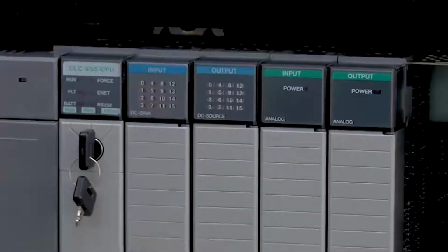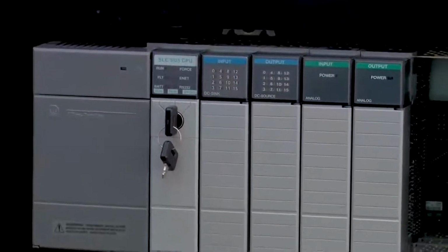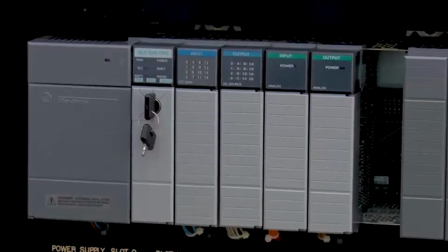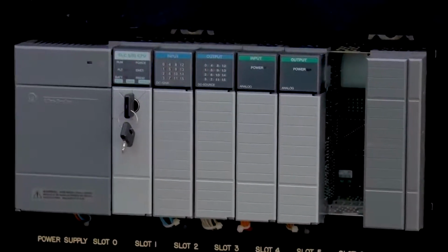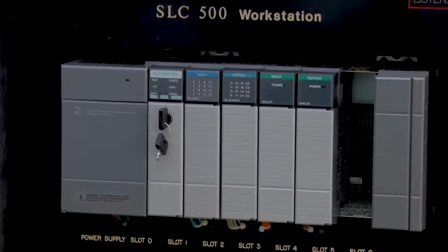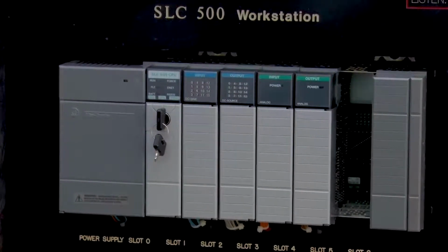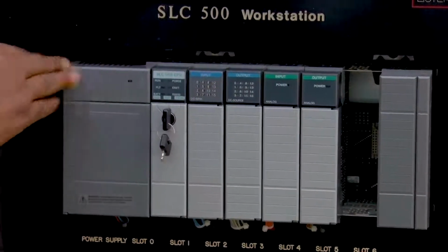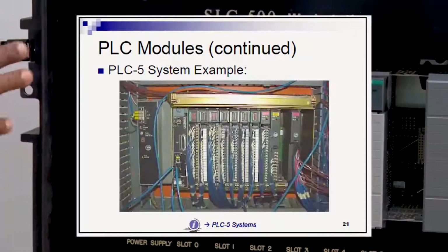Okay, so in general, before you pull this out, you have to shut down the PLC so as not to introduce static charges to the printed circuit board, which can actually damage the PLC. Okay, so this is one of the products of the Allen Bradley PLC.